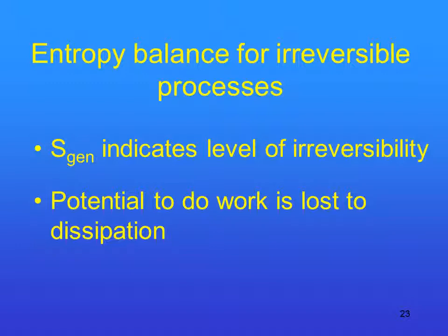When we looked at that turbine problem, the entropy was generated in the irreversible case, and the friction went into dissipation, meaning it was turned into a thermal type energy, which is not easy to get the work back out of. In fact, it's impossible to get all the work back out of the energy once it's dissipated into a thermal form.